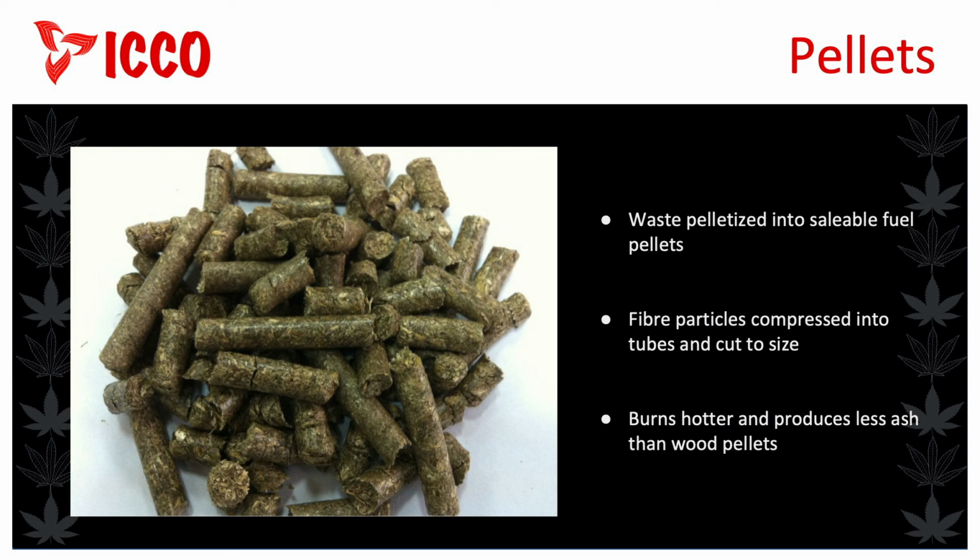The fiber will have to be chopped and perhaps ground to achieve the desired particle size to make different types of pellets. After the pellets are ready to go, they are fed into a pellet mill using a conveyor. The pellet mill can be of an extrusion type, where the machine forces the particles through small holes to form compacted tubes of particles, which are then cut to size.